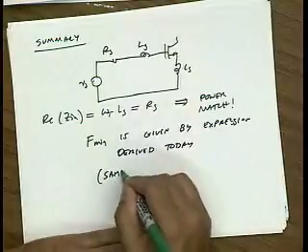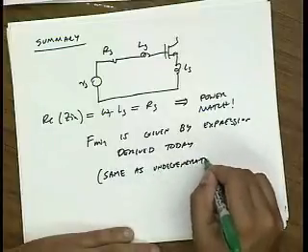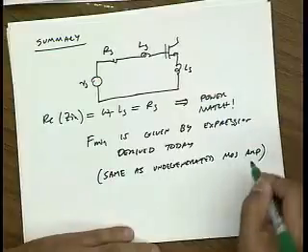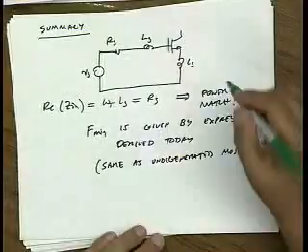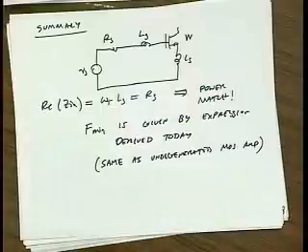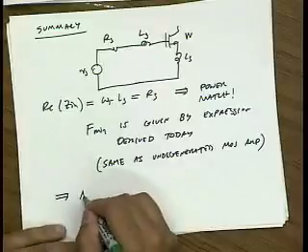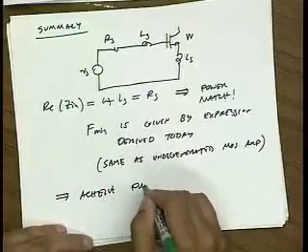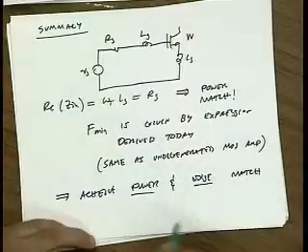The important point is it's the same as the undegenerated MOS amplifier. And so it turns out that if you're willing to sweep things, you can play around with your device size and find the device size such that the optimum noise figure source resistance is also the same as the power match. So this allows you to achieve a power and a noise match.